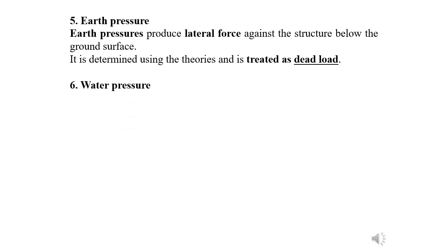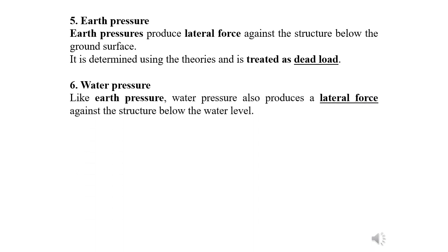Water pressures. If you are going to construct a tank, the water is also going to apply lateral pressure, or horizontal pressure, on the walls of the water tank. The water pressure will also be there, so that also you have to consider.